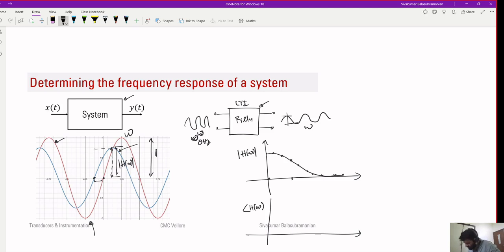So you simply measure this. If you take this as time t equals 0, this is some negative time delta t. This delta t can be converted into phase if you know the frequency of your original signal. Let's say the original signal had a time period of capital T, which was 2 pi by omega.